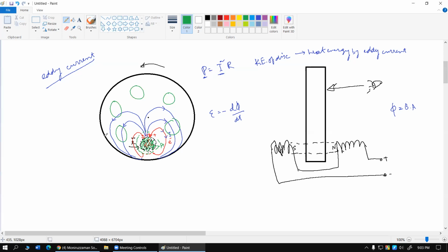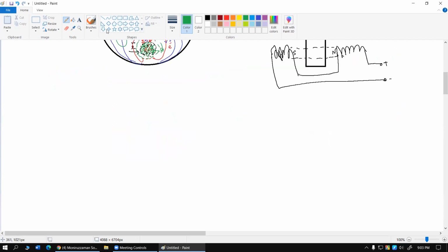What you need to understand is that over here, we applied the magnetic field, for example, within this small circle. Here, the EMF was created, and the other space, which is outside this circle, this region of the metal disk, was utilized for the flow of current. If we introduce a uniform magnetic field across the whole disk, then this eddy current will not exist. Let me show you an example for that so that you better understand it.